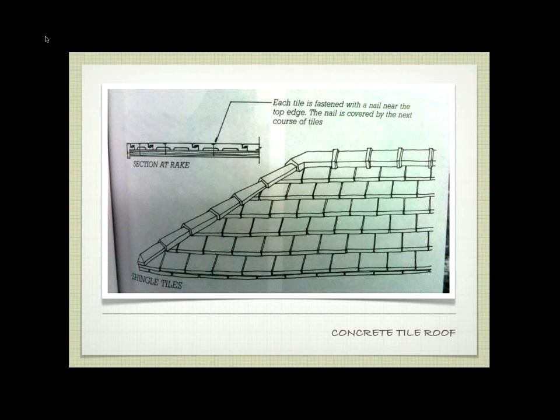One side note, I had a job where they had these kinds of tiles. The house was built in the 80s, and they wanted to do a remodel and kind of an addition to the house. And when they did it, they needed to extend the roof tiles. The problem was they didn't make those roof tiles anymore, right? So sometimes if you go into this concrete tile realm, you can end up not being able to match a roof tile if you want to add later on. So it just depends on if the company that made the tiles in the first place went out of business.